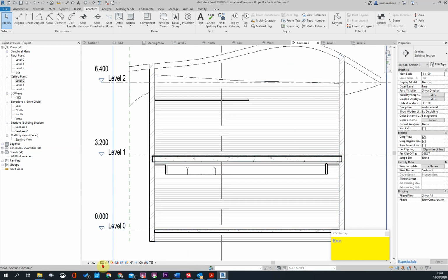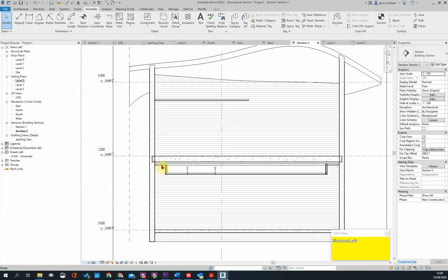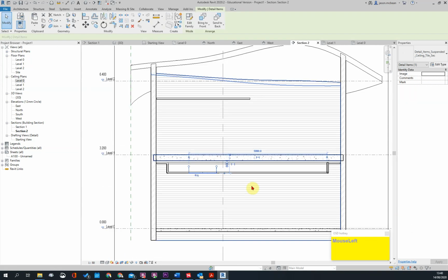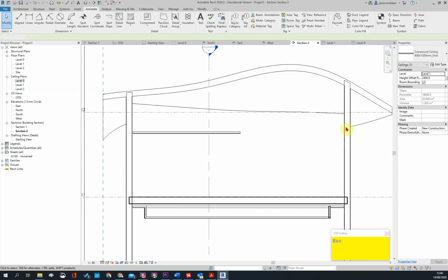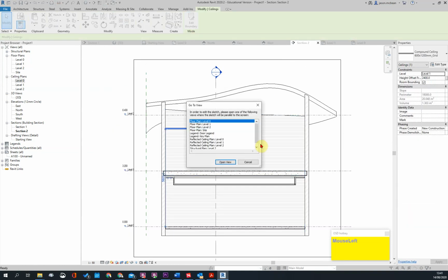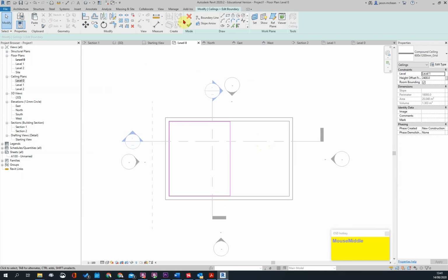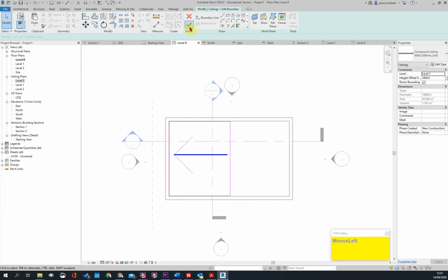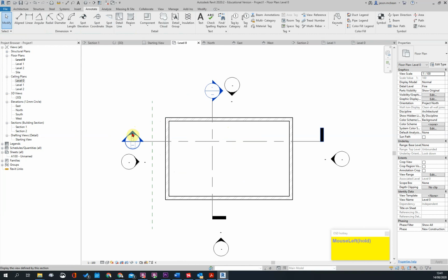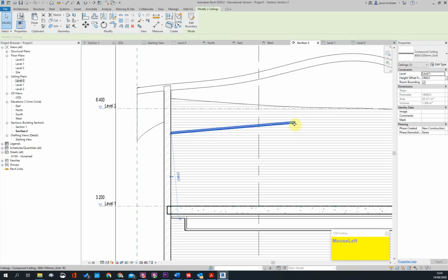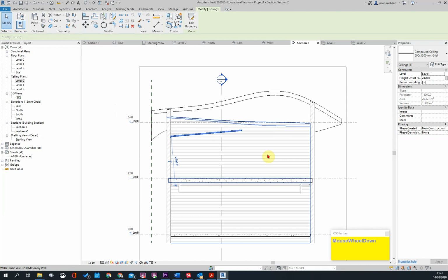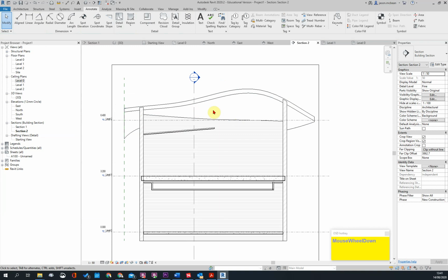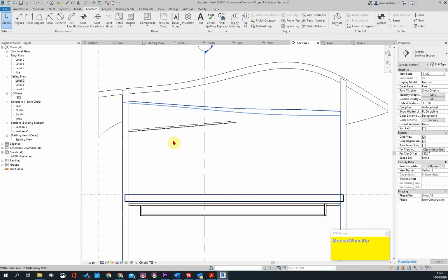Okay, we'll just have to join these walls, change the scale to the correct scale, 1 to 50. Okay, that's a half ceiling. Here you could have a flush ceiling. These ceilings, if you go to edit plan, you can add, so you can make them slope in a direction as well. Okay, but here you have to work on head and tail, and I'll show you what that looks like. So if I went into this view over here, so it starts at 0 there and goes to -3. I usually pick a line and then work out how much it falls, and then, especially if you've got a ceiling that runs along a sloped, you can slope ceilings. Okay, so that's definitely doable.